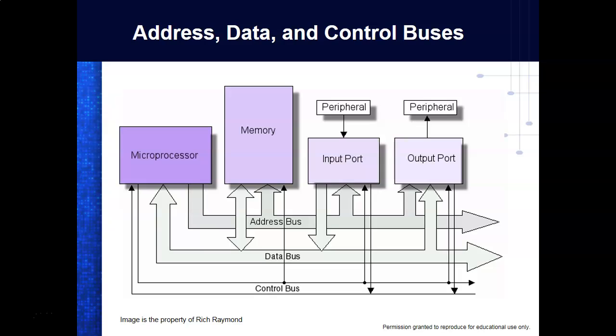Well, you got to have some way to compensate for that speed. So we move through portals. We have input ports, portals. A portal is an entryway and an exit way. And then we have output ports, and we have I/O ports. There's actually 3 different ports we could run into. And so the address bus selects everything. So they select every port, everything. Then the data bus is where the actual data transfers, and the control bus controls the direction. And there's multiple pins. I've only shown 2.